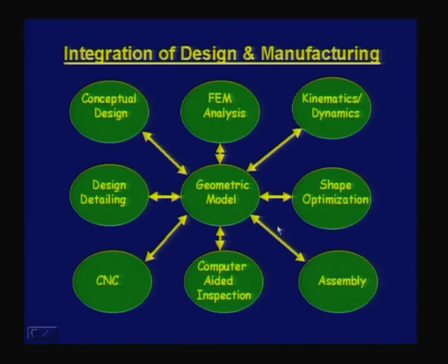It is true that in manufacturing activities also there is a feedback which is sent to the geometric model for changing the geometry. We discussed what is called design for manufacture and design for assembly. So, in DFM and DFA, what one is trying to do is carry out the manufacturing operation either in the real world or a virtual world, then based on the feedback you are trying to modify the geometry or suggest some changes so that a component can be manufactured in a more optimum manner.